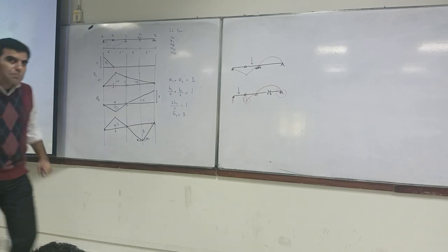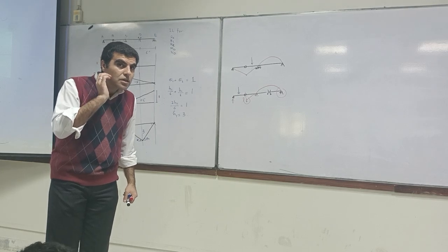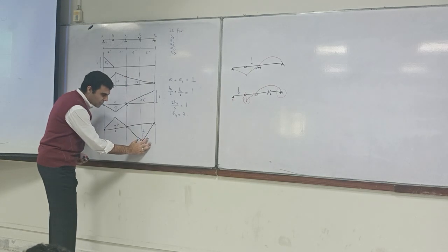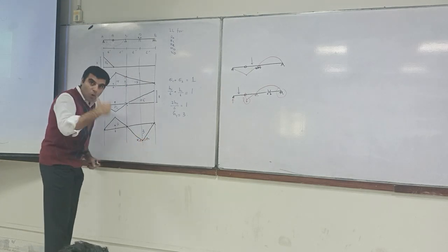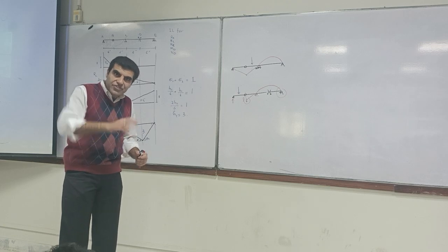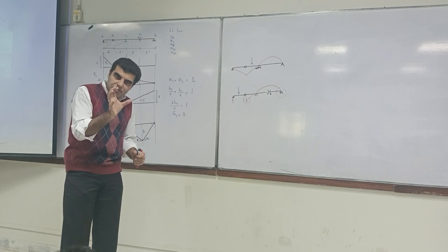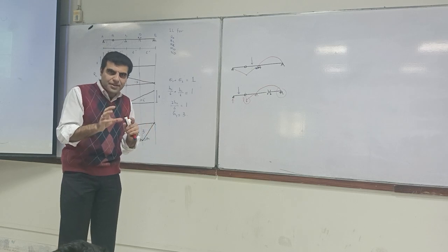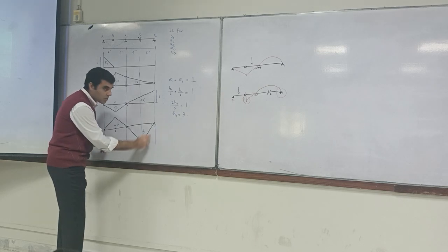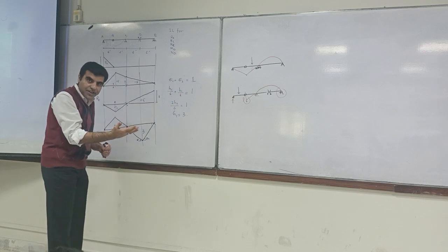Sorry, speak up please. What unity thing? Sir, until now we have been moving a unit. So I'm saying that when you move it over here, the moment has the corresponding deformation in terms of theta. It's a rotation. Moment will give you rotation. So that rotation must be equal to 1. Theta 1 plus theta 2 must be equal to 1. That is for moment, isn't it?